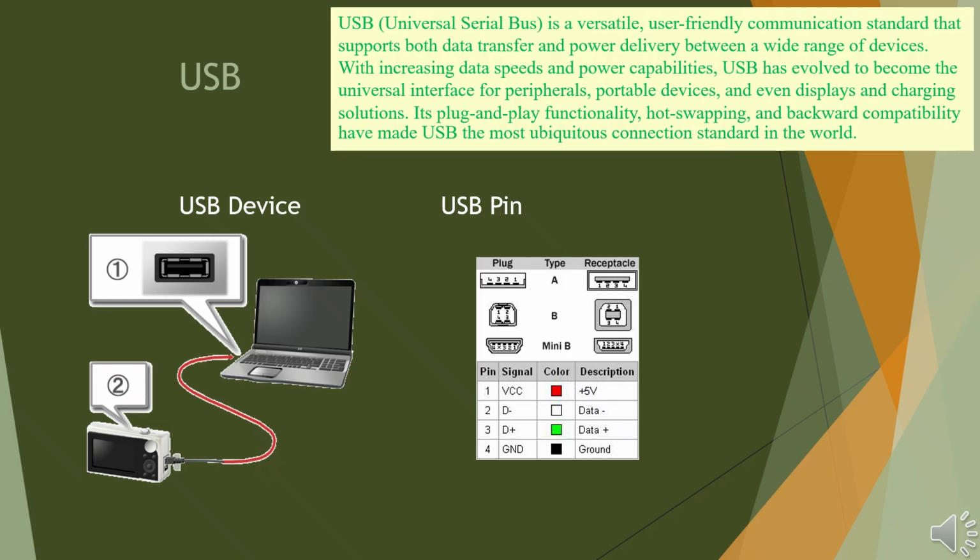In embedded systems and mechatronics, USB is often used in three key roles: programming and debugging interface, such as connecting an Arduino or RP2040 board to upload firmware; communication link, for serial data exchange between a PC and microcontroller, using USB to UART bridges like CH340 or CP2102; peripheral connection, where the microcontroller acts as a USB device, e.g., appearing as a keyboard, mouse, or virtual COM port.